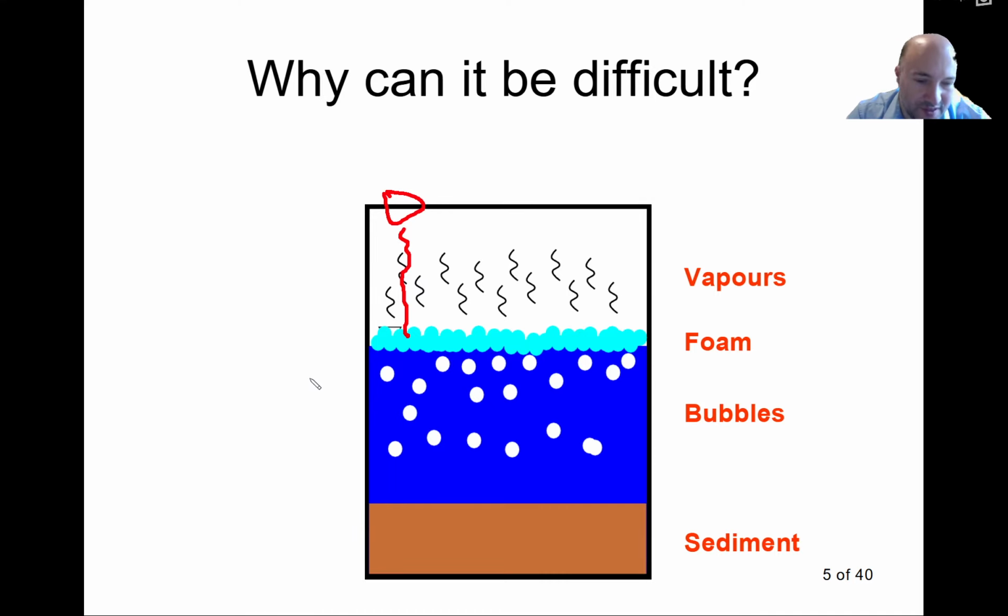On the bottom of the tank we can have some sediments. So if we have a sediment and we install a sensor from the bottom, such as a pressure sensor, it may get blocked by the sediments. Then we may add high temperature. So we may have a liquid with quite high temperatures that would be able to destroy our pressure sensor or any kind of liquid level sensor that we have directly submerged into our liquid.